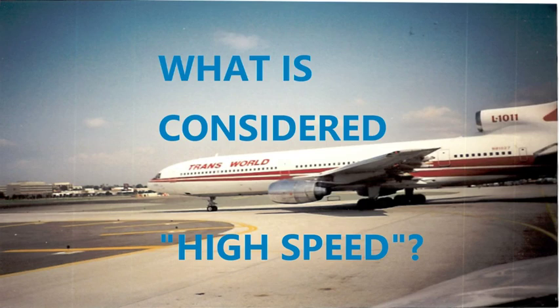It could be just right below Mach, or even lower than that, but we're talking about enough speed that compresses the air around the aircraft. The danger with that is it changes the density as a result, and it also creates these shock waves. And all of that can affect the lift of that airplane, and also the drag.